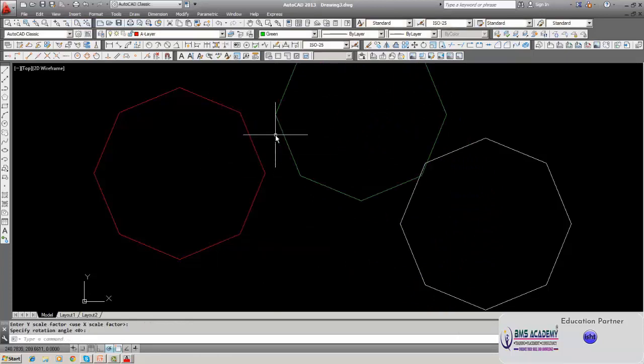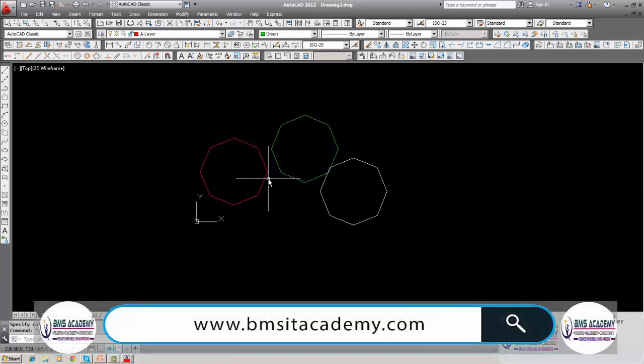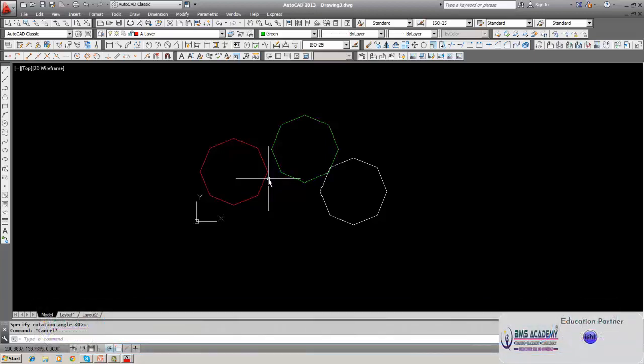So one more important property: when you create a block drawing by the command W block, and then open that block in some other drawing, it picks up the layer in which it was created, and the new drawing will have another layer which is the layer of the block on which you created.